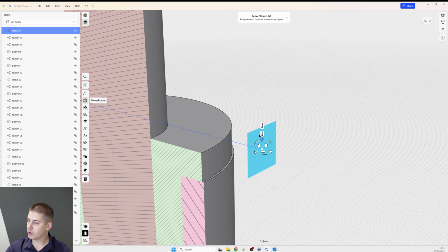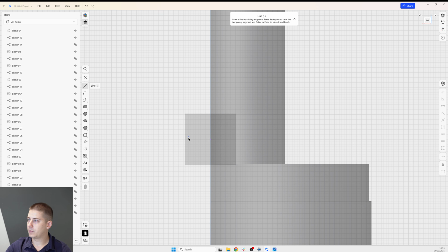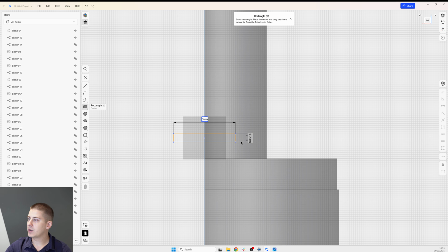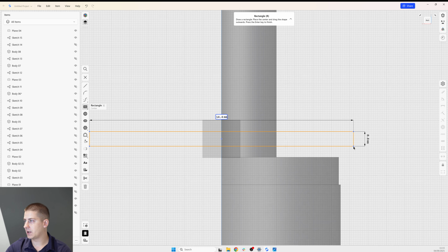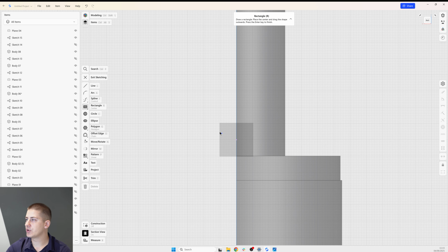And now I'm going to use this to create profile. So in this case we could achieve the same result with extrude feature, but if we wanted to create some shape which is not rectangle, if we wanted to create some curved shape or something like that, this would be the better approach.